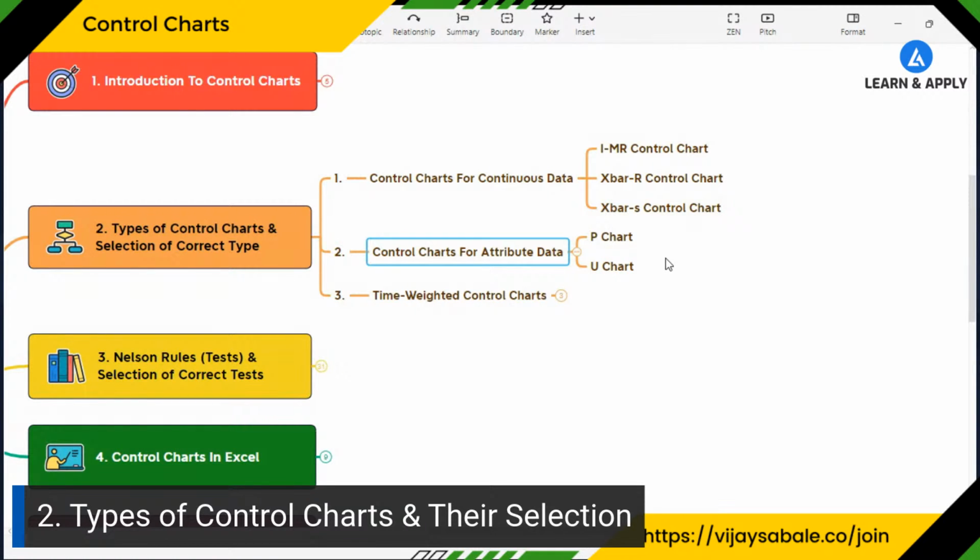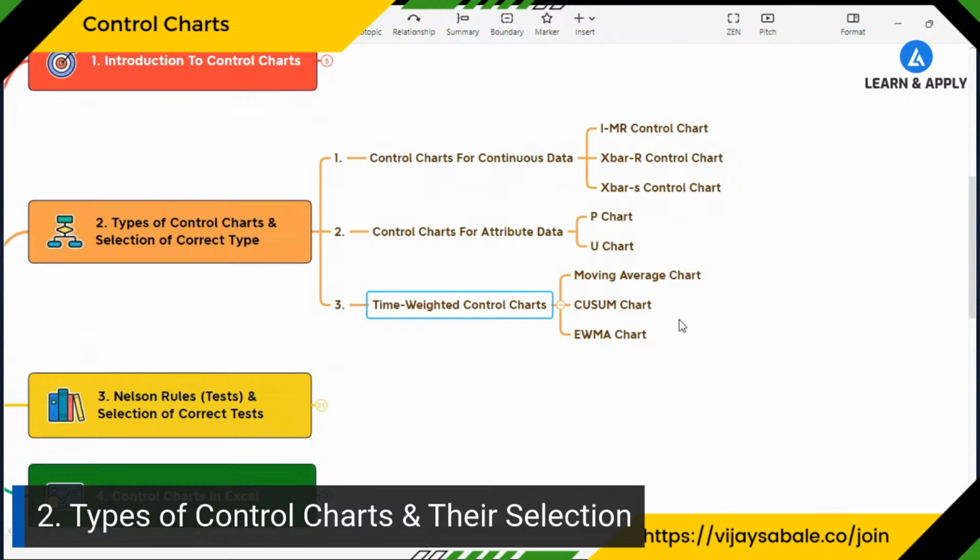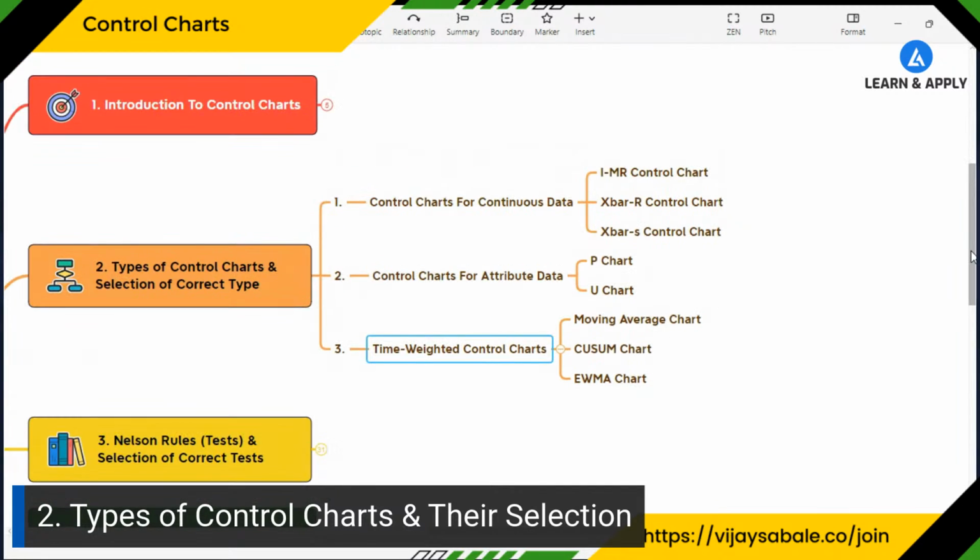Again, there are NP and C charts also, but these are the two main charts for the attribute data. Now, if you go for the time weighted control charts, these are very sensitive and they have the ability to detect the smallest variation in a process as well. The main control charts are the moving average chart, CUSUM or cumulative sum chart, and EWMA chart. So we can use these charts when we are looking for smaller differences to be detected, right? So this is again a very important topic, which control chart we should select based on our intent or based on our data and the application.